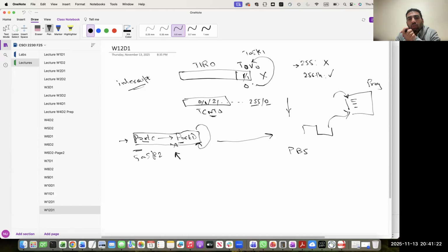But the interrupt allows you to continue doing something else, and once the event happens, for example, the setting of the overflow flag of timer 0, the microcontroller will automatically jump to a location where you have already stored a program, and then it will execute that program. That program will do whatever it is supposed to do. For example, in this case, we have placed a program here which is responsible for generating a square wave on the pin PB5. Okay.